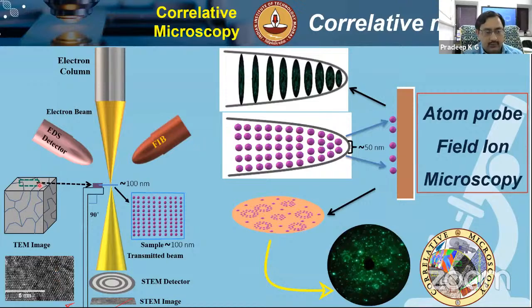Therefore, at this moment, we have all the capability to do it on a bulk scale, in a micrometer scale, with cross-sectioning by selective focused ion beam milling and look through the third dimension also by imaging. And if required, we can go to the nanometer scale and look at them. And further, we can go to almost the atomic scale by imaging using these atom probe tomography methods.